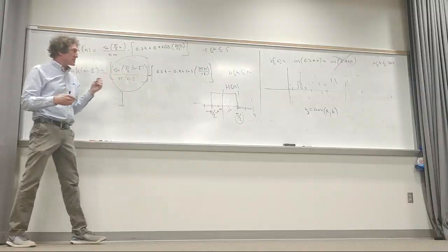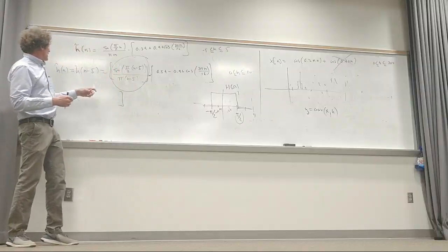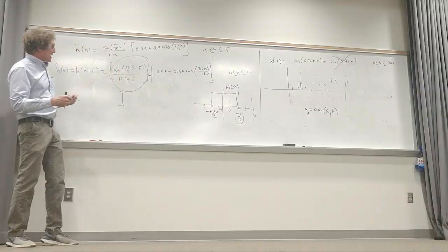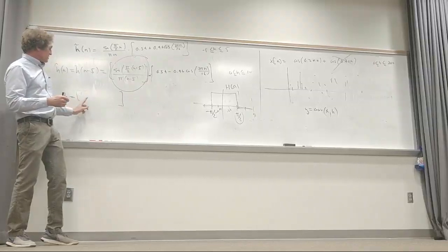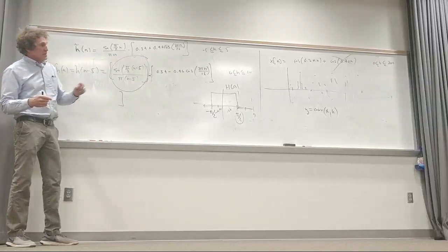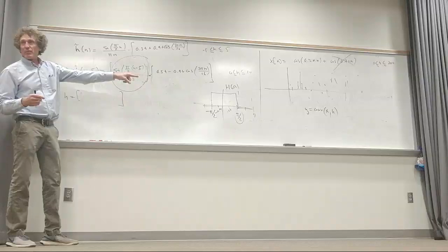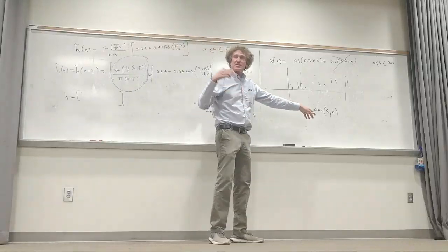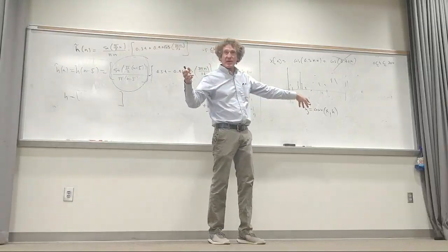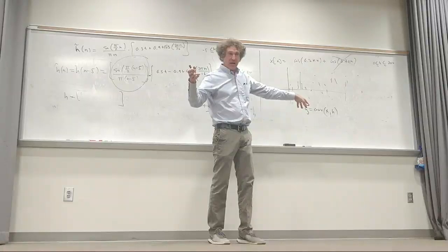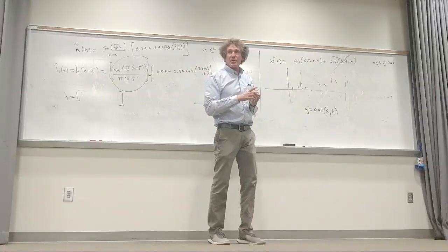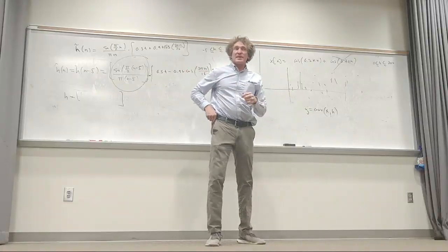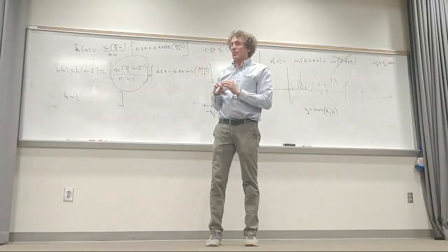Then once you have this right here, you can generate those points and simply do a convolution to get all values of output y right there. And I'm going to tell you right now, it's going to have 5 extra values in the input because it is time delayed by 5. That's the one thing and the only thing that we really care about. Everything else is right. It's the correct impulse response. And it's amazing how good this kind of a filter works.